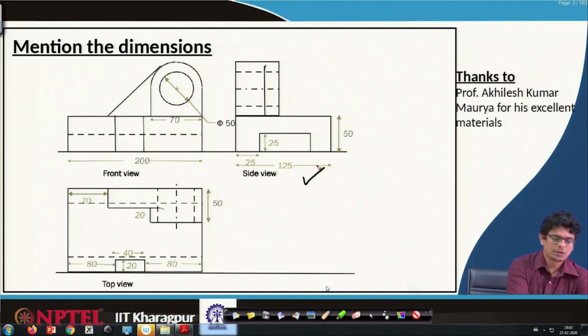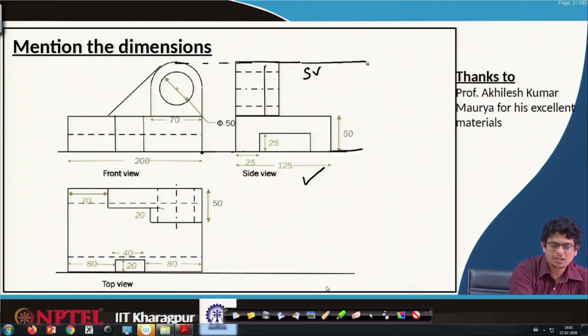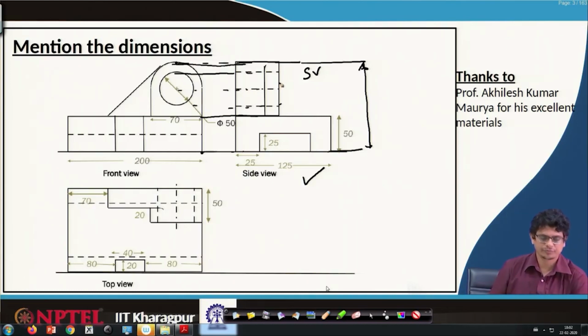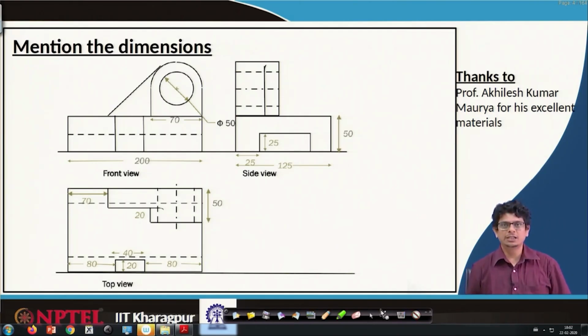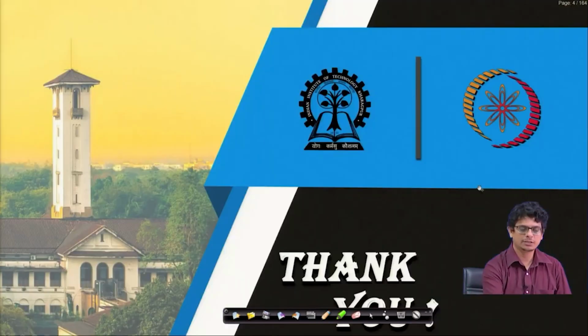Here we have to observe the top view lines and the front view lines coincide here, and the side view will be completely bounded by those lines. This object will be projected here and this circle will be projected here. The center of that circle goes there. In today's class, we will look at more details about the front view, top view and side view for different objects.